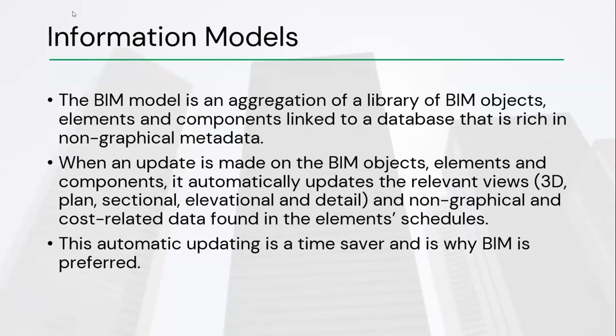So if you are involved as a quantity surveyor, it is important that when the BIM execution plan is being developed at the earlier phases of the project, you communicate to the project team that you're going to use these models for quantity takeoff. And this is the software that you are using to do quantity extraction. These are the file formats you would expect to receive from the engineers and the architects.